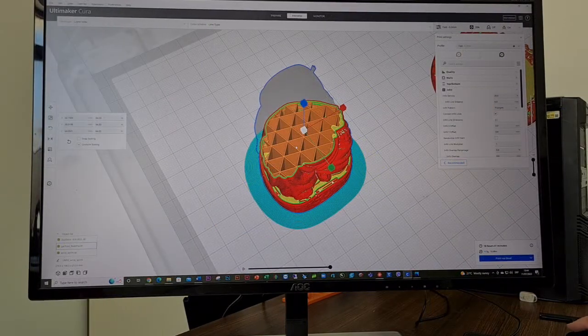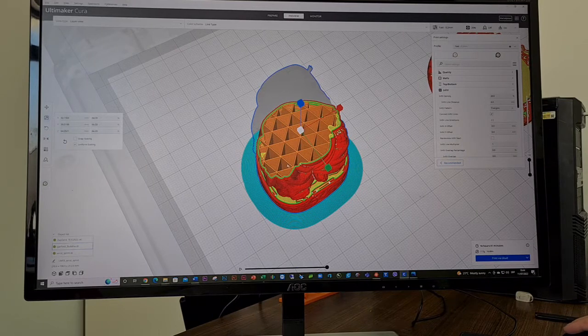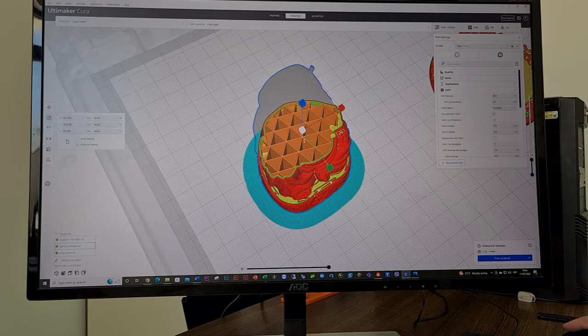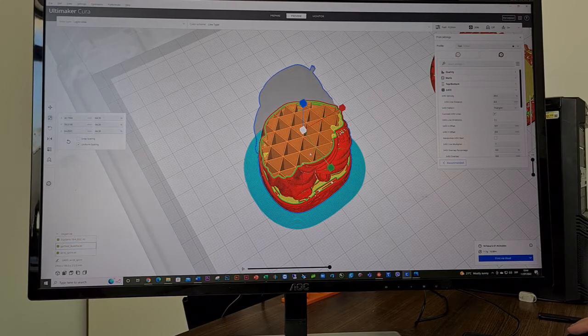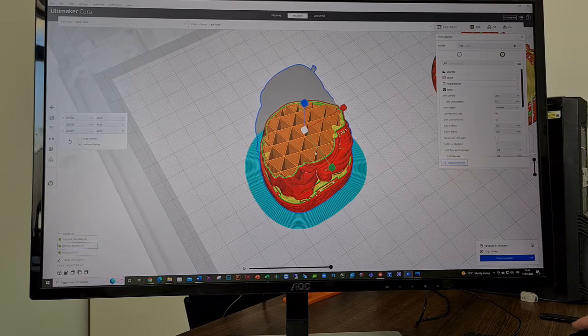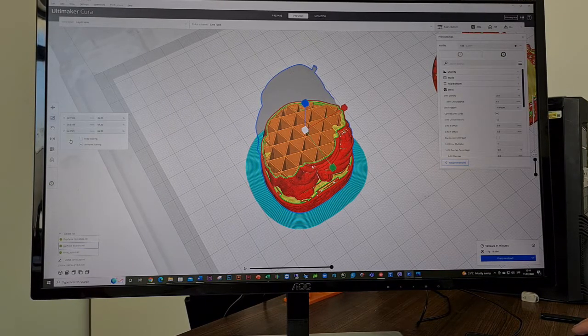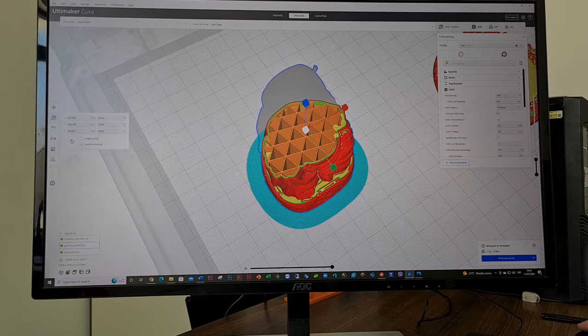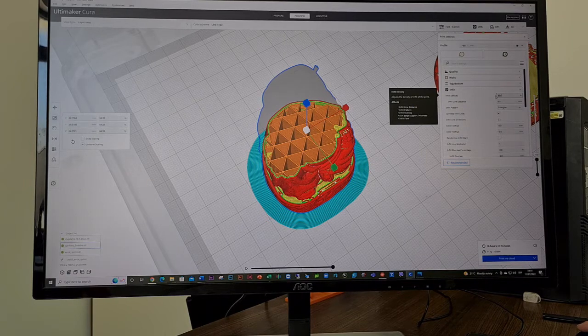What is one of the advantages of FDM technology is that you can choose by manipulating the software the infill percentage of the body which you will produce by 3D printing. What does it mean? For example, practically, if you want to design and manufacture some object which will not suffer high amount of stress or load or force applying on it after the production, you can increase or decrease the percentage of infill.